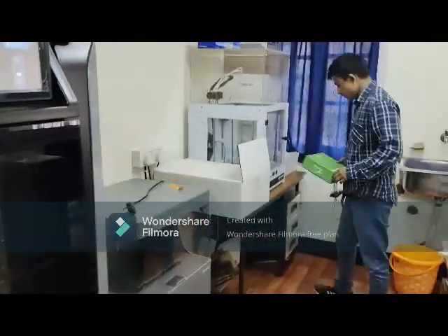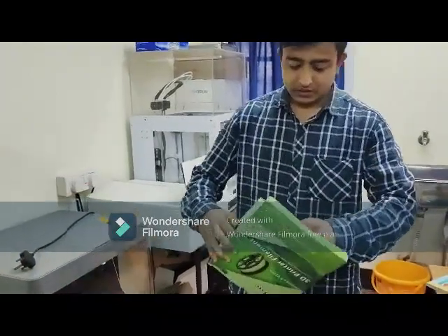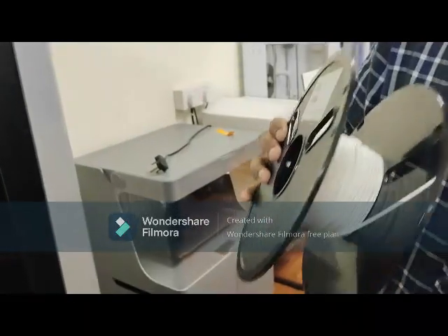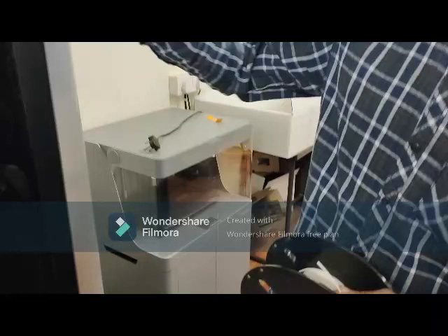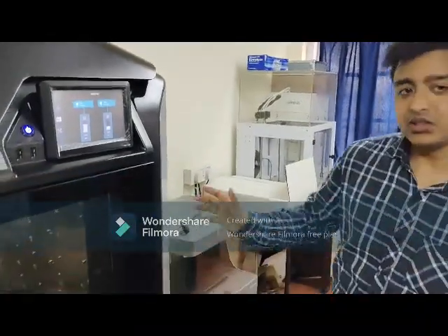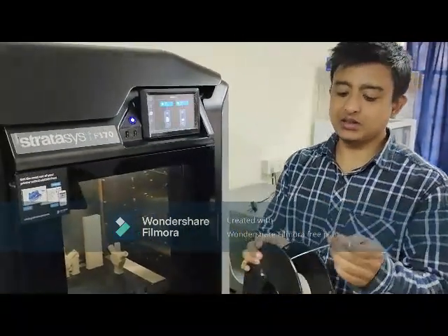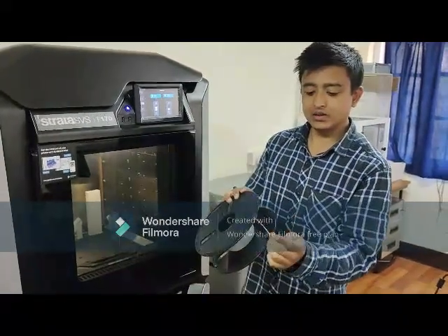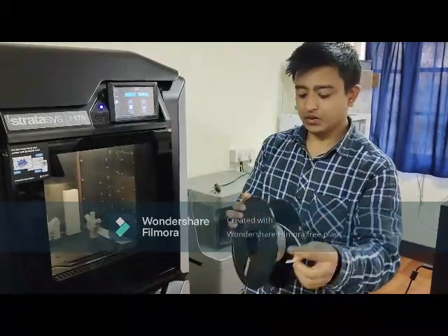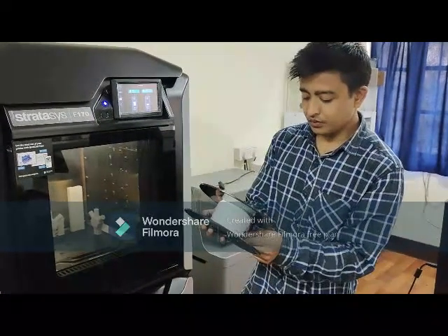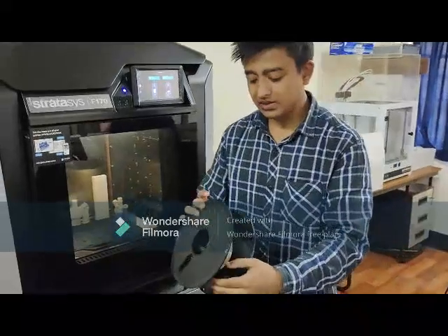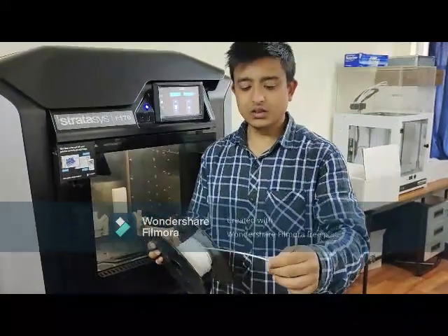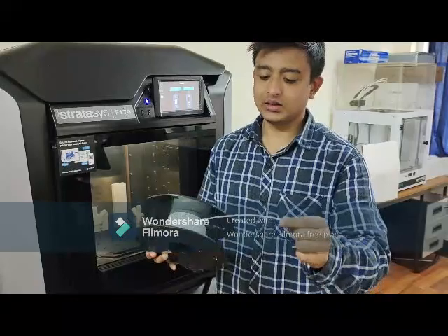Fine. So this is the material we have here. This is called the spool. The entire section is called the spool, and this is the filament we have here. In all these three machines, this one and that one, we are using this kind of filament. This is a PLA material. This is a PLA filament, and this is the size of the filament, you can see. The diameter is 1.75 mm. This is the diameter of the filament.